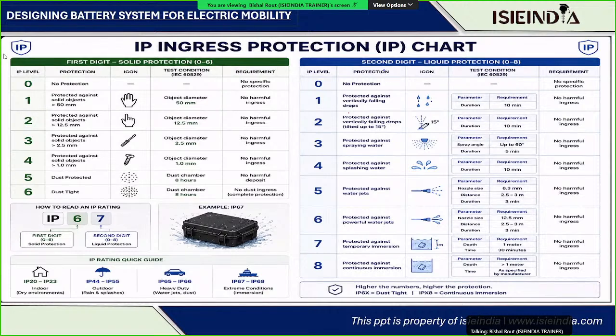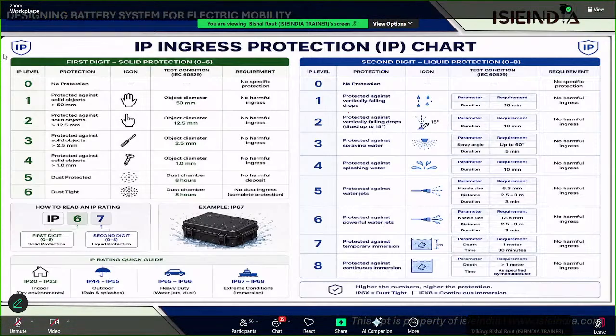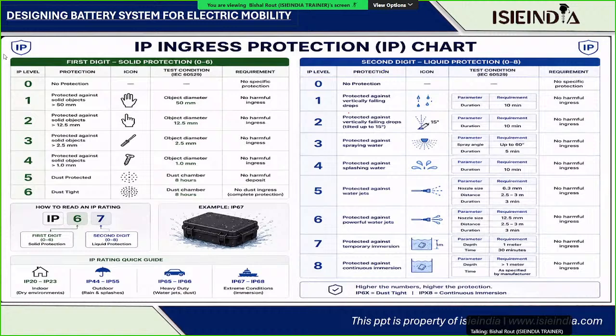That is because while applying the overcurrent, the battery gets damaged. So multiple destructive tests are required and multiple pack samples get destroyed, and that is the reason why redesign may occur, lab charges are high, engineering manpower is required, and documentation effort is again very high, then your pack is certified. So that is the reason, right?